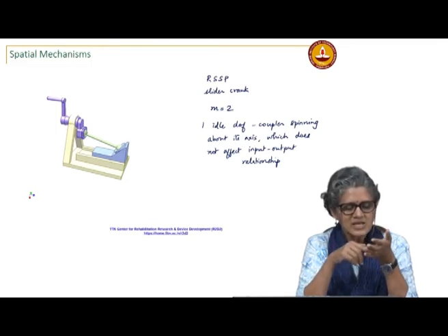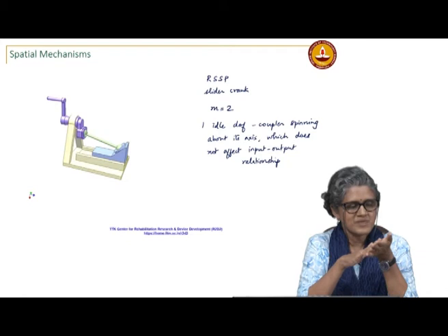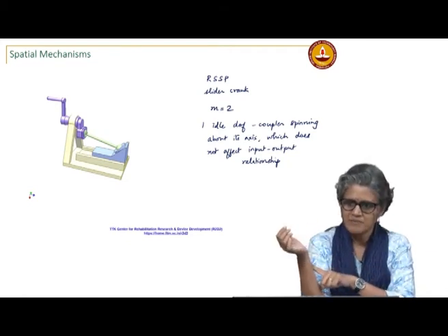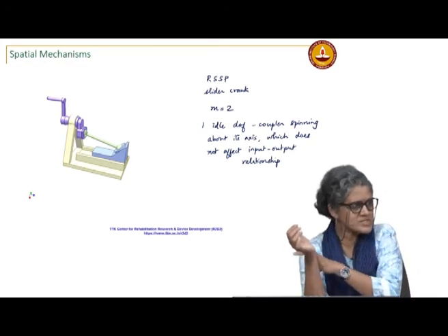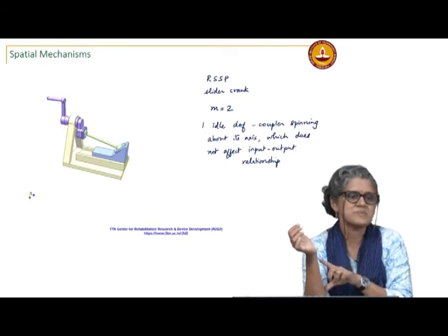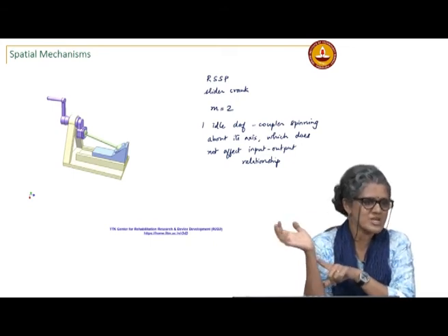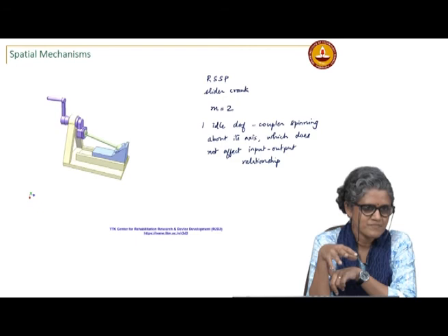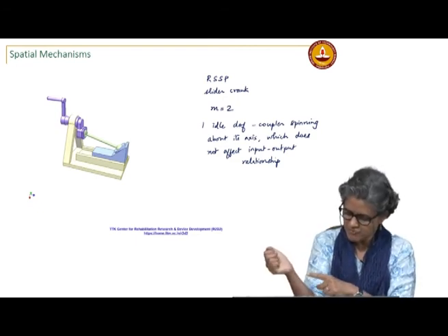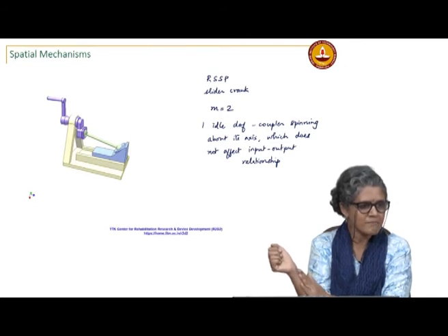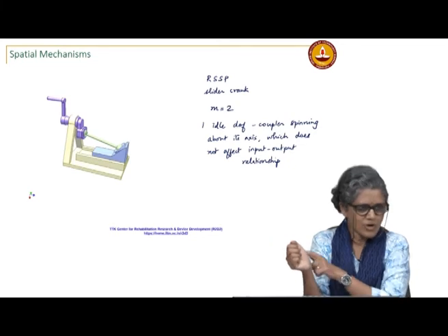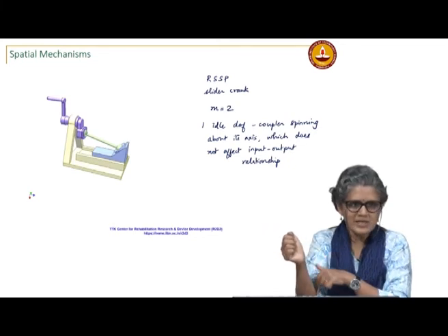The reason it is convenient is that if there is a frame rigidly attached to a link, all the points on that link can be easily described with respect to that frame, and it is not going to change as the linkage moves. So, if I have a coordinate frame attached to my forearm, I know exactly where my wrist is with respect to that, or elbow or any other point on my forearm.